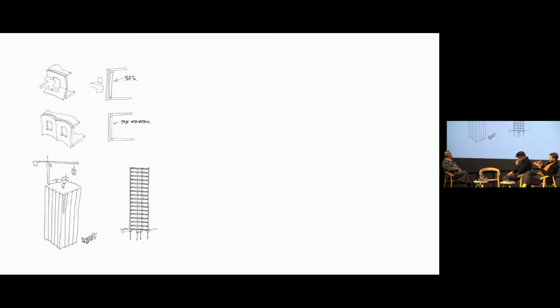And particularly the idea about using bricks on the sides of buildings, so if the bricks aren't load-bearing, clay bricks expand, they move quite a lot, you need a lot of movement joints and shelf angles. Most buildings or large buildings clad in clay bricks paradoxically support the walls, the frame and the floors support the walls rather than the walls supporting the floors, which is completely perverse within the context of 10,000 years. So the superstructure gets even bigger. Foundations get even bigger.